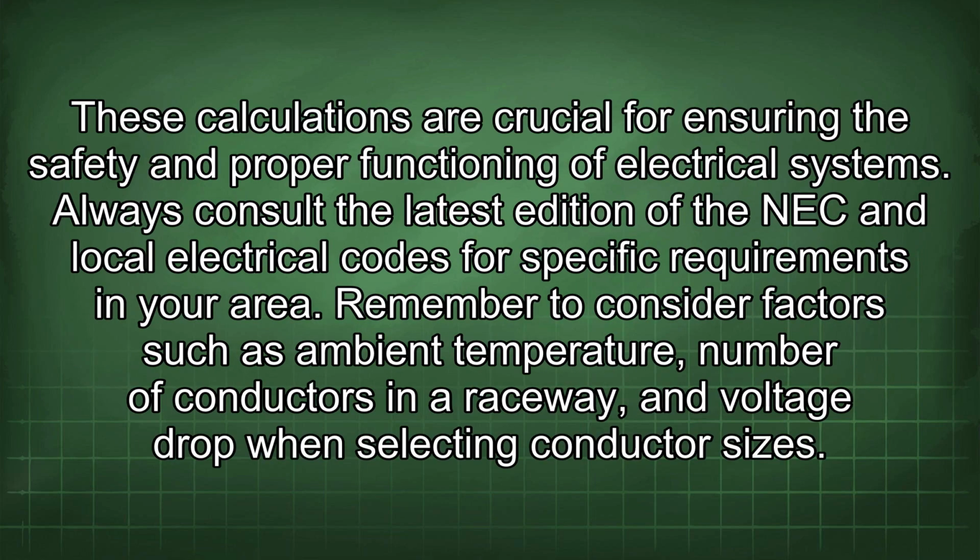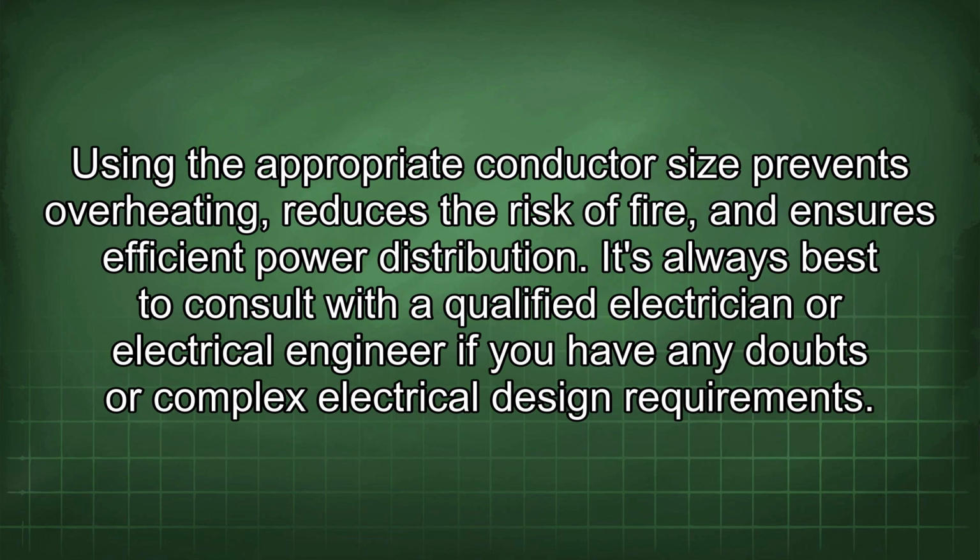These calculations are crucial for ensuring the safety and proper functioning of electrical systems. Always consult the latest edition of the NEC and local electrical codes for specific requirements in your area. Remember to consider factors such as ambient temperature, number of conductors in a raceway, and voltage drop when selecting conductor sizes. Using the appropriate conductor size prevents overheating, reduces the risk of fire, and ensures efficient power distribution.